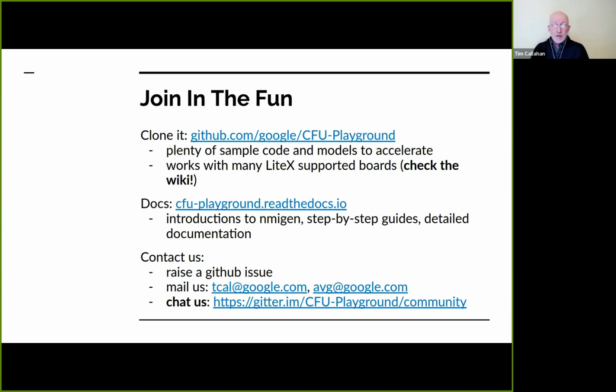Well, running on the board, you can always compare against a non-accelerated version, an apples to apples comparison, with CFU and without CFU. We use a completely accurate cycle counter, and we also have additional counters that you can control, pause and restart for counting cycles. That's actually one of the main benefits of running on the board. You know that you're considering all the delays from memory contention because you're counting the real number of cycles that you're running.